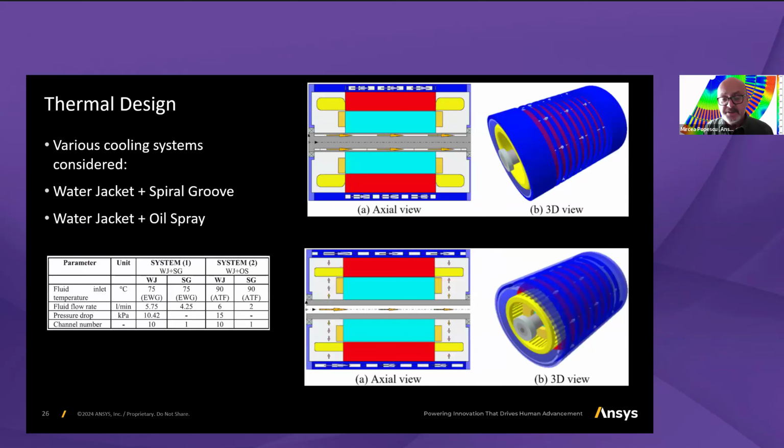In the same design, we investigated two possible cooling solutions. The one on top, it's very similar to what it's in induction machine e-tron, as well, maybe a bit similar to Tesla, meaning that ethylene water glycol fluid was circulated through the rotor cooling, and then from the rotor through a pipe, it was circulating inside the stator water jacket, and then from there, the same liquid was going to the inverter. So the same fluid was used to cool both the machine and the associated inverter.